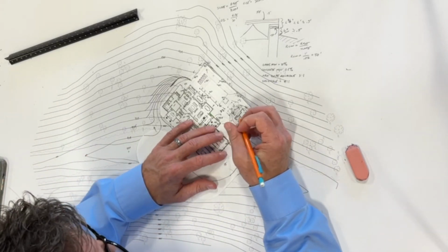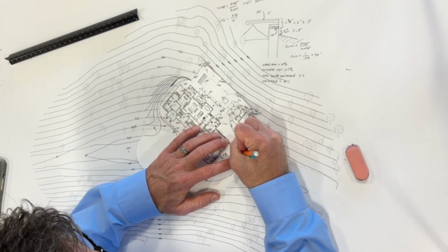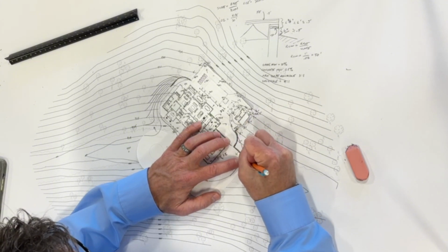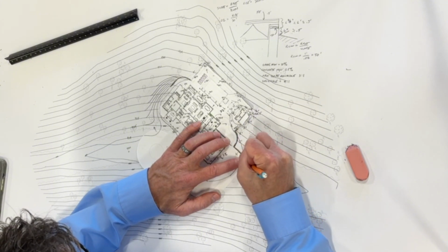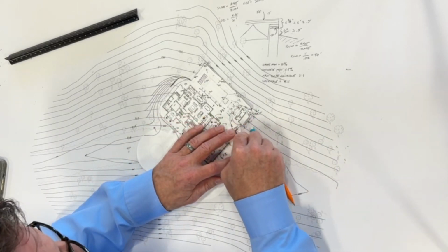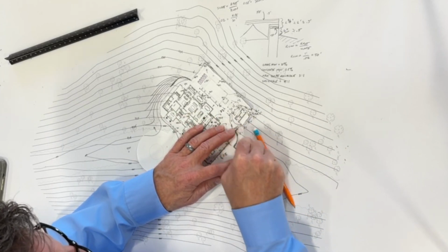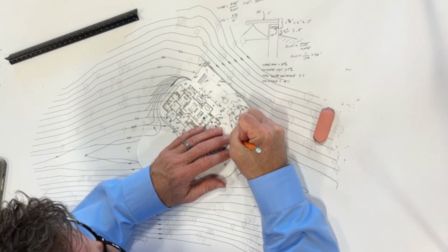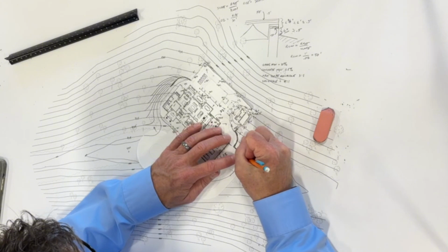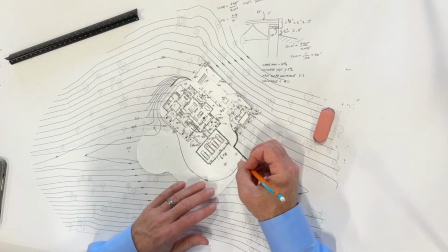So what that means is this is a 940 contour. So that means this wall now comes like this and comes around this driveway, right? And then the 940 does not come down here because that's crossing over the retaining wall. Retaining walls are wonderful to make grades work. It's just they are costly. So now the 940 is in the retaining wall, and then it comes out of the retaining wall right there.